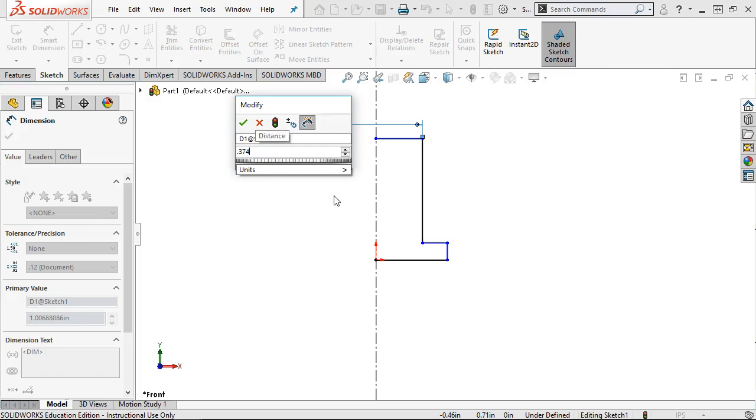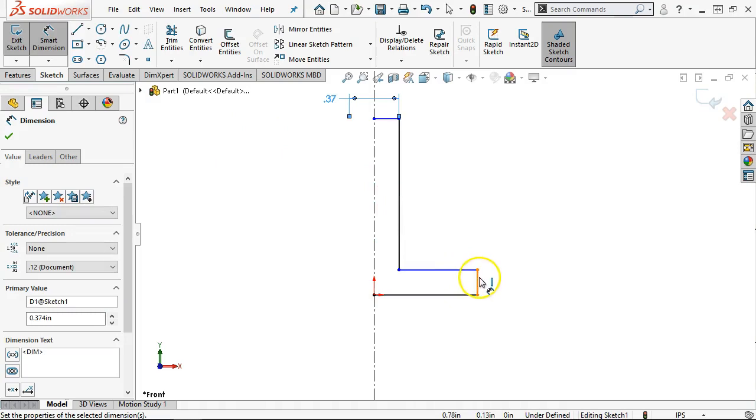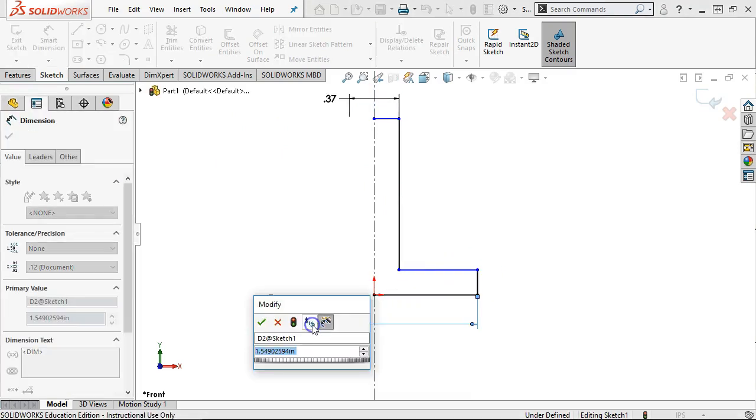374, and so the consideration is I don't want to have to press this into the bearing, through the housing, through the bearing, and into the other housing. So I'm not concerned about it turning, spinning on this shaft. When I sandwich the bearing, it should still just be the outer race that is doing the spinning with that pulley attached to it. So if we go 374, it didn't quite adjust as much as I thought.